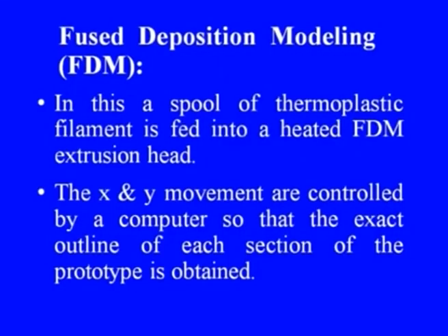Next, let us discuss another important technique, that is FDM, fused deposition modeling. In this, a spool of thermoplastic filament is fed into a heated FDM extrusion head. The x and y movement are controlled by a computer, so that the exact outline of each section of the prototype is obtained.